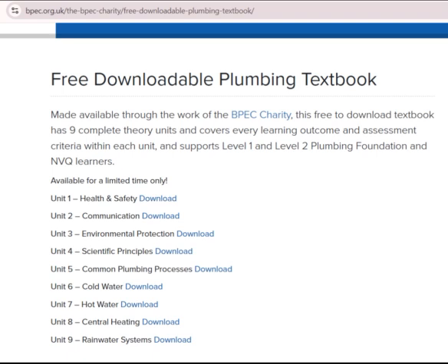AC 5.10 Identify the insulation requirements of central heating system components. Pipework. All pipework in the roof space should be insulated in accordance with the Water Supply Water Fittings Regulations 1999 to guard against freezing.